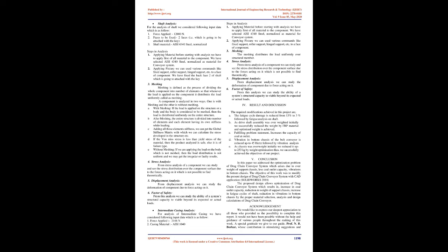Below are important component analyses which help to reach the objective. Shaft analysis. For the analysis of the shaft we considered the following input data. 1. Force applied, 12,000 N. 2. Faces to be fixed: 2 faces, i.e. which are going to be attached with the key. 3. Shaft material: AISI 4340 steel, normalized.